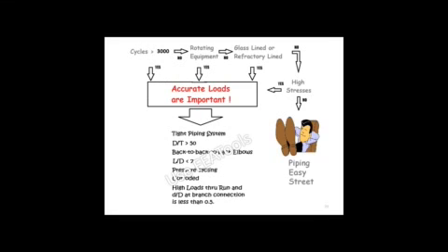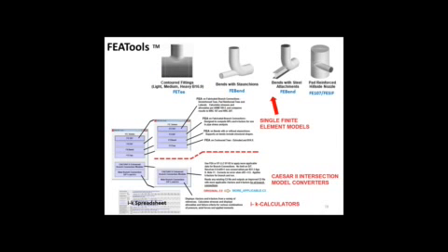So this is just the two-path process that we've talked about. One of them is no high stresses, no rotating equipment, low D over T's, no cycles. You're on easy street and you're solving relatively easy piping models. If you don't have any of those conditions, then FEA Tools is a big help. Here are the things that FEA Tools does. It has individual finite element models for contoured fittings, for bends with stanchions, for bends with steel, for hillside nozzles, for pad reinforced hillside nozzles.